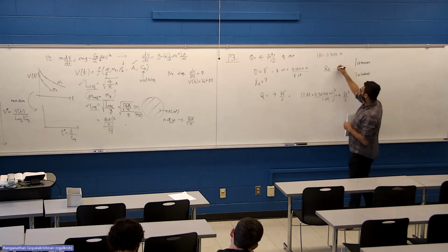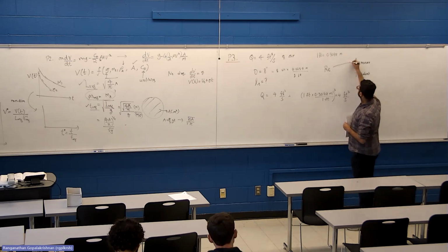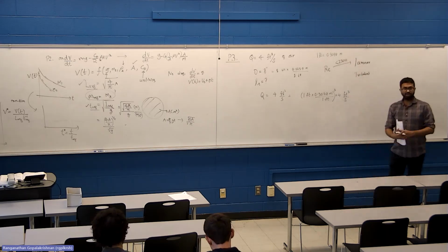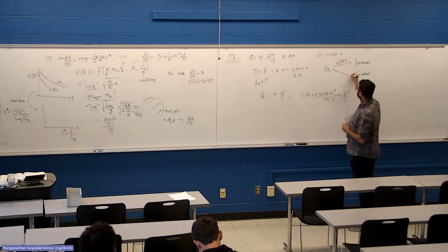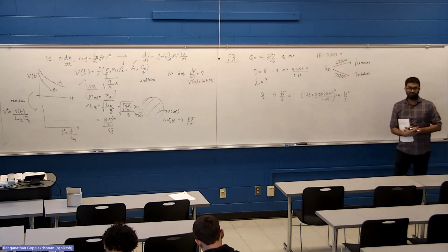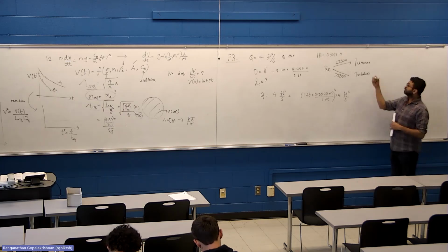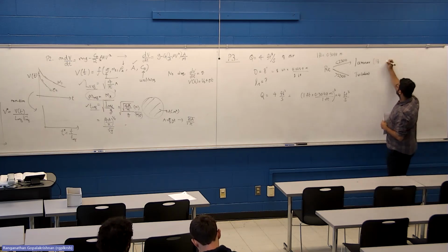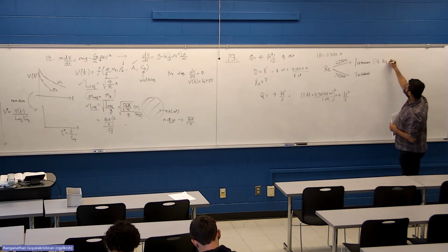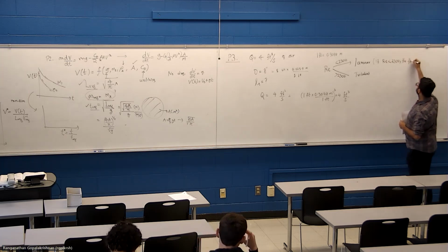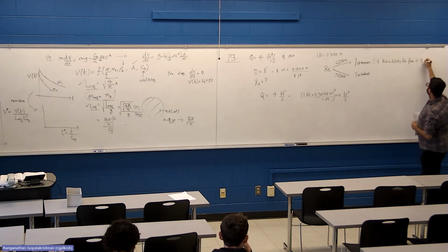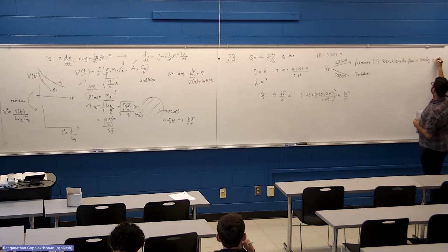2300. So you compute Reynolds number. If that happens to be below 2300, it is surely laminar flow. That's what's been experimentally observed so far. But if it is more than 2300, it is very likely to be turbulent flow unless special care is taken. I'll write it here. It's a good moment to repeat this. If Reynolds number is less than 2300, the flow is strictly laminar.